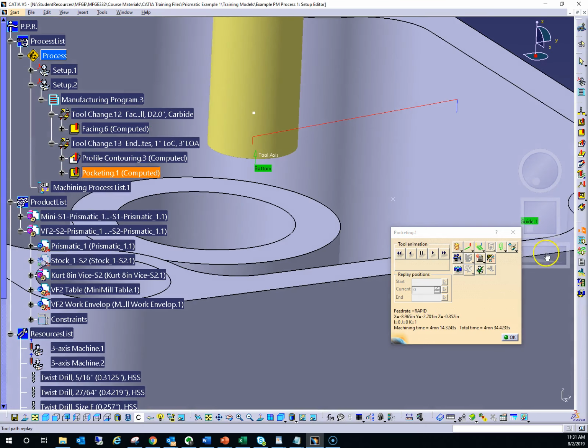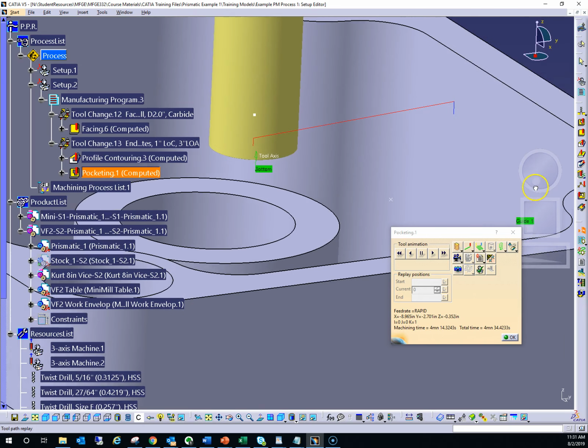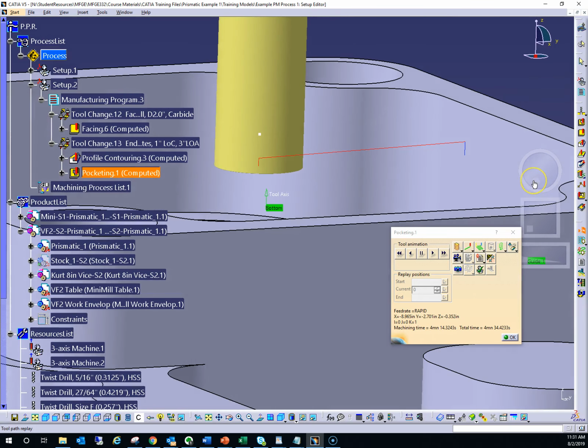So by adding that helical approach, we're gradually bringing the tool into the material. We're avoiding a direct plunge, which is always harder on the tool. It's a move-in that has X and Y motion to it too, not just the Z. And we're ensuring that this rapid move stops 25 thousandths before the tool enters the material.